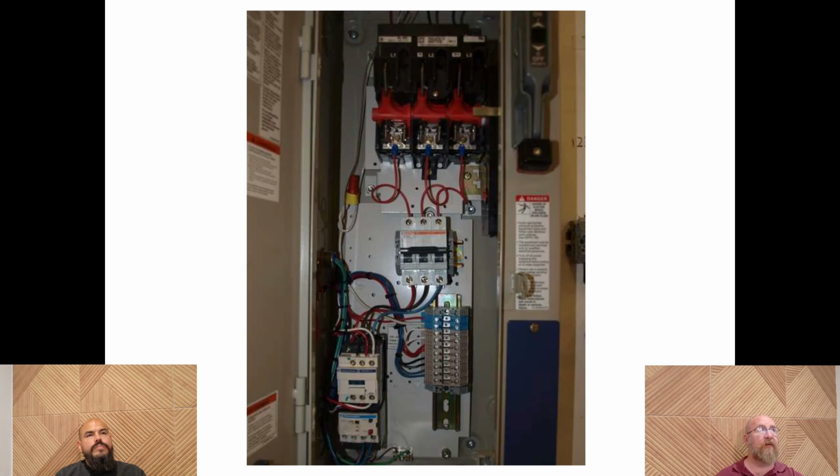So here we have some stacked protection. Here we have fuses up at the top. We have a circuit breaker in line with that, because those two functionally do similar things, but fuses pop with higher voltage. It is current too, but you can get them to pop fast. Whereas circuit breakers, it's almost entirely current, and you can reset them. That's the big difference, right? We can reset the circuit breakers, but we can't reset a fuse. Once it's gone, it's gone. You've got to replace it.